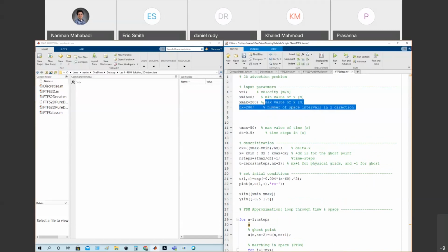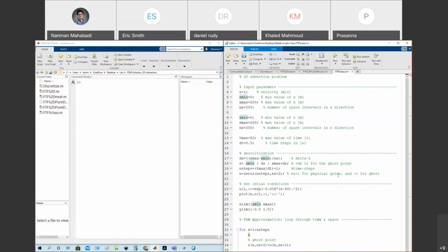And it's pretty simple. Just copy this section and paste to add for y, right? And I'm just gonna modify this for y max, and number of intervals in y. As this is a symmetric kind of problem, everything should be the same. Maybe you need to just modify the descriptions, right?